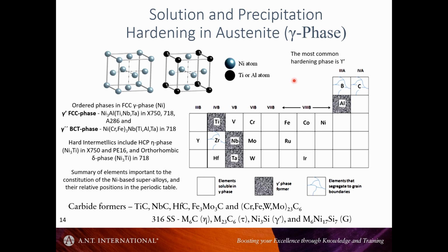And that's why basically nickel alloys which are hardenable by the formation of gamma prime, that elevates the yield strength very substantially, and that's why these materials are very good for springs. So although their ductility may be reduced somewhat, their yield strength is elevated substantially through the inclusion of the gamma prime precipitates, and yeah, they're then difficult to deform, but are also very good then spring material.